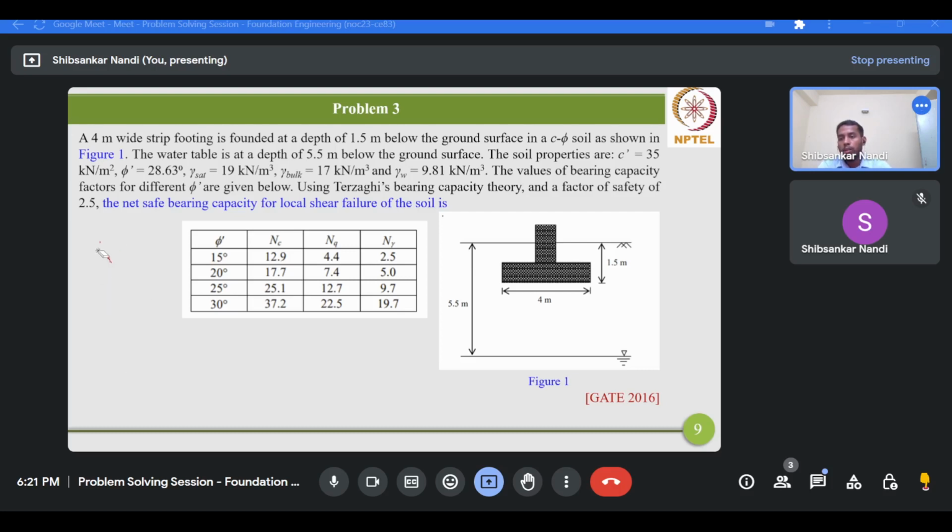Now, from the failure zone in case of local shear, this failure zone is clearly defined only below the foundation, and adjacent to that it is poorly defined, and again there is a slight bulging as compared to the general shear failure. Therefore, you cannot assume the mobilization of the shear strength, cohesion, or friction angle for the entire length of the failure surface.